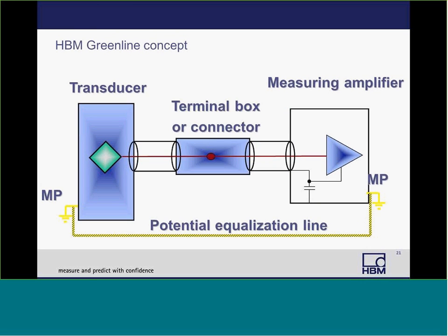Now there can be problems with Faraday cages, and this will be a very common theme with noise. Just because one solution works in one area does not mean it will always work in another. And generally troubleshooting noise tends to be a trial and error exercise. So, as we said before, use the Faraday cage. Well, there are problems that can occur. And one of them is if there are potential differences, the compensating currents will flow across the cable shield, and this typically will cause a 60 Hz interference.